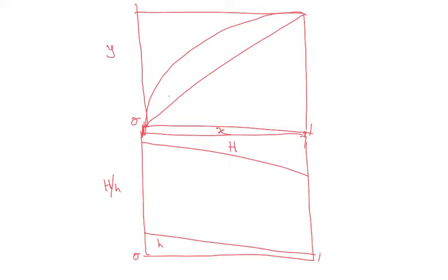For example, you know your x value and you want to draw tie lines on this curve. How do you draw it? Let me change the color. So what you would do is, for every point, or you can choose some points, let's say we were drawing a tie line corresponding to this point. That point is actually a line on the enthalpy concentration curve. It's only a point on the McCabe-Thiele diagram, but it's a tie line.